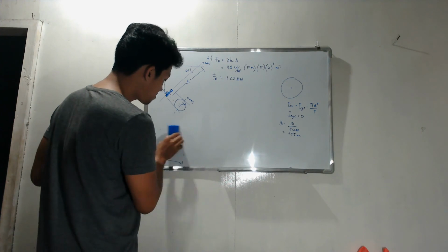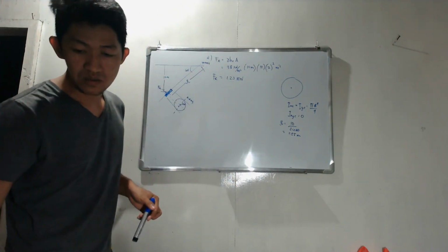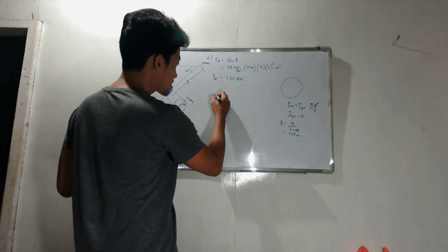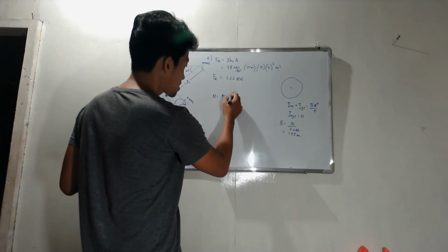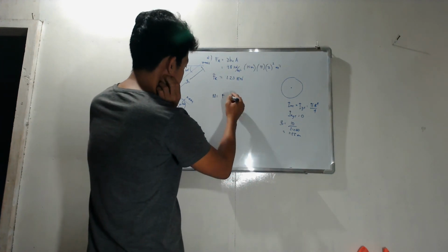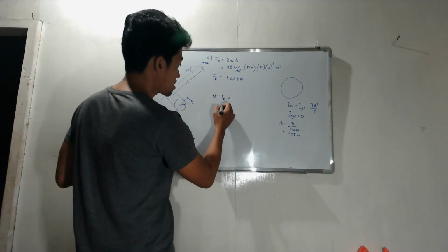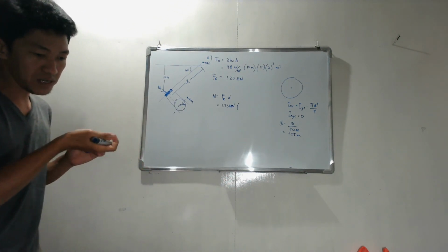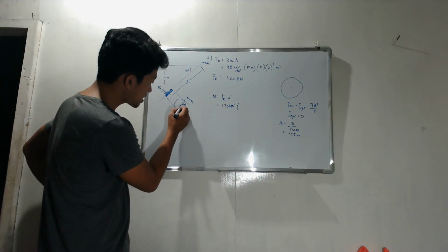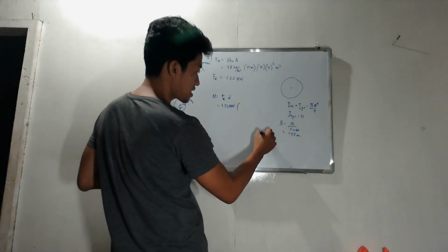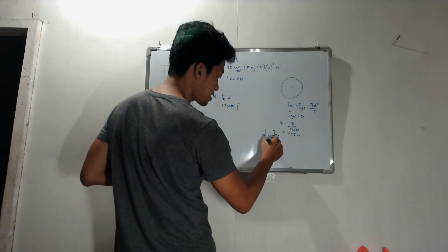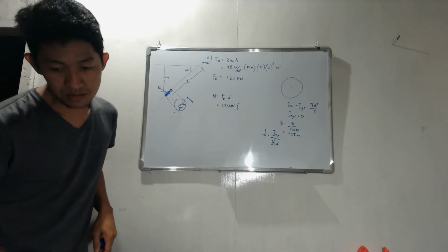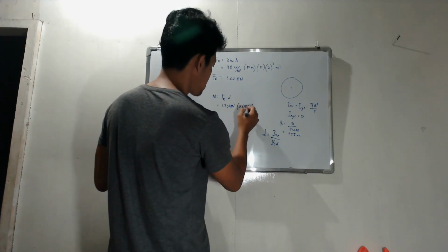By the way, this is a continuation of the problem. The question is how much torque or moment should be applied to open the gate. If you recall, moment is just force times distance. The force is the resultant force, 1.23 meganewtons. Multiply it by the distance D, which is the value I sub xC over y sub C times A, and that is 0.0866 meter.